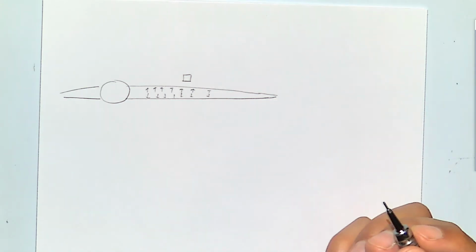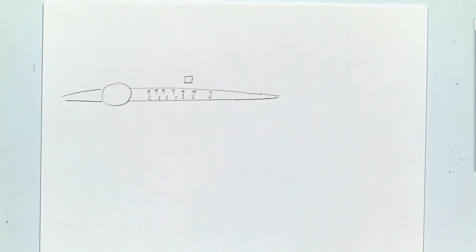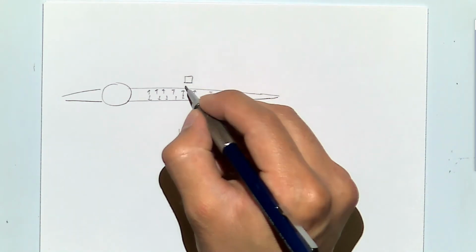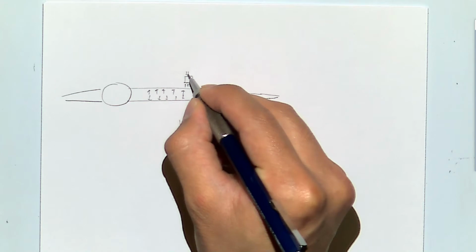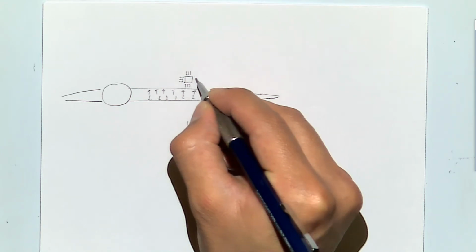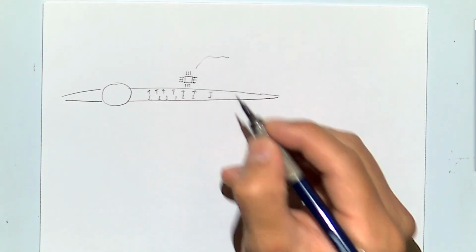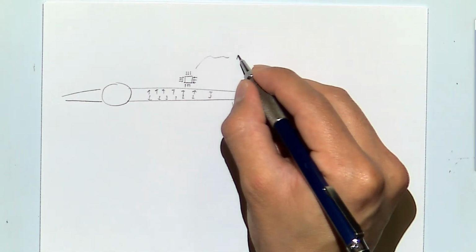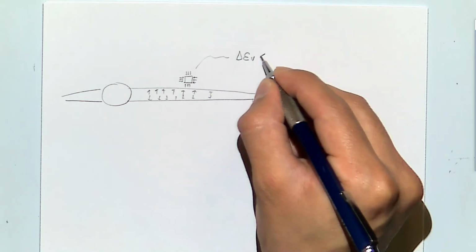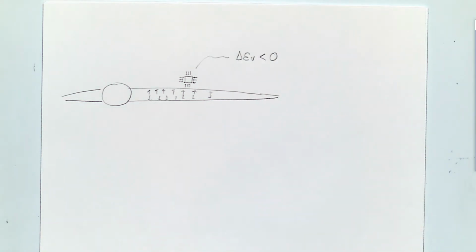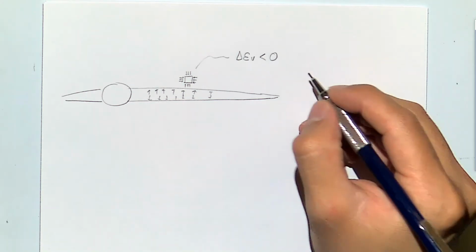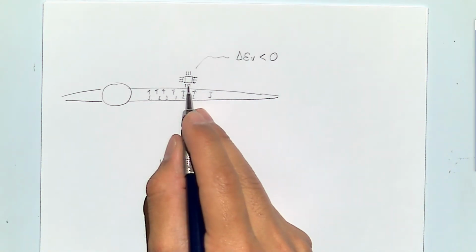As you increase the stresses, you cause changes of shear stresses, changes of normal stresses, but in general, what you will have is a change of volumetric strain, which is a contraction. If you have a contraction and you have a very low permeability,